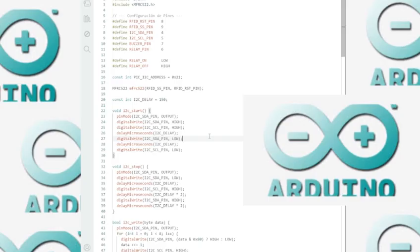At the beginning, we define all the pins we are going to use. This is crucial for organization. Note that the relay pin is defined as RELAY_ON with a low value, because this module is active low. We also define the I2C addresses. Here, you can see it. In the setup function,